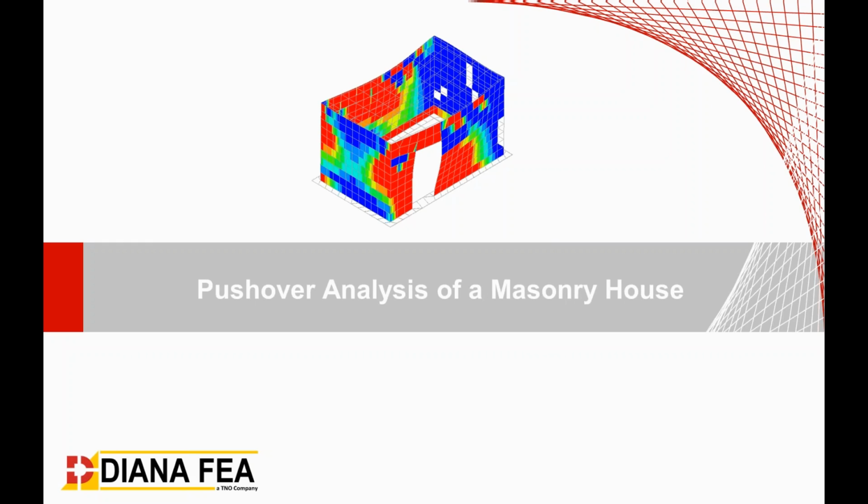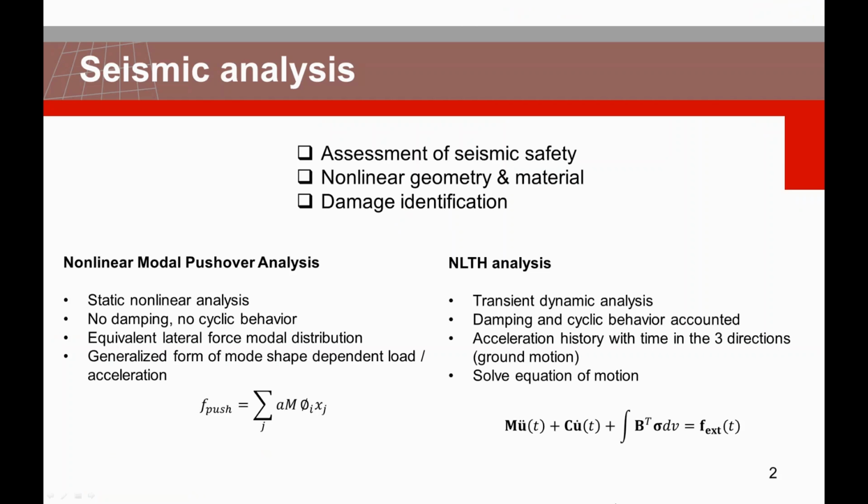So let's start with a brief introduction about seismic analysis and a comparison between pushover and full nonlinear time history analysis. Both methods are used for assessment of seismic safety, and they both account for nonlinear geometry and material response, and can also be used for damage identification.